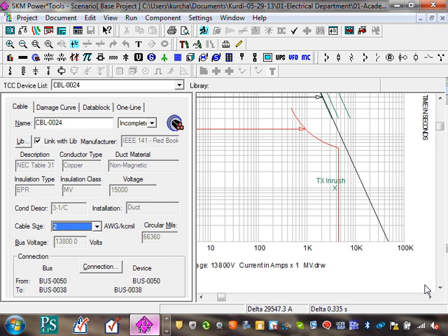Mind you, I'm using an IEEE cable. I don't know how many of you have paid attention, this is a 5,000 volt cable. That's a big deal when it comes to cables higher than 600 volts, versus 600 volt cables or less. Speaking of which, you guys know in 2014 they changed the voltage limit? Anybody heard that? You no longer say over 600 volt or 600 volt or less; it's over 1,000 volt or less.